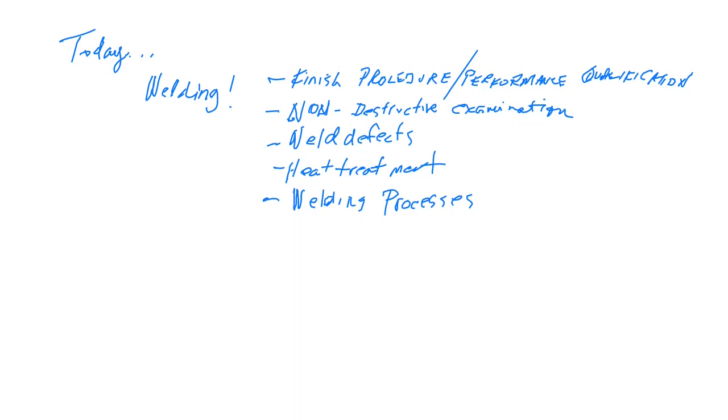But welder performance qualification, basically, we've got a welder that welds to a procedure. And the welder must prove that he or she is competent at welding a particular procedure before doing an actual production weld. They can practice all day long, and a lot of weld shops permit the welders to practice, give them an hour or 2 hours every day for a week, so they practice a procedure before they actually go to the weld test center and do the test so that they'll pass the test.